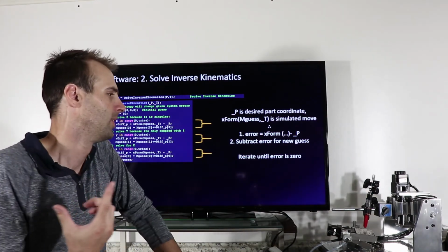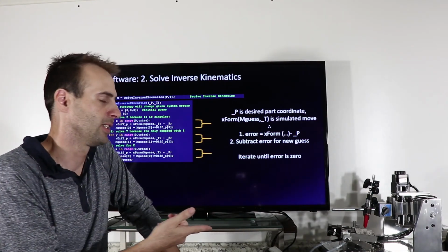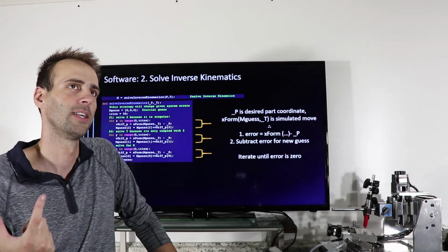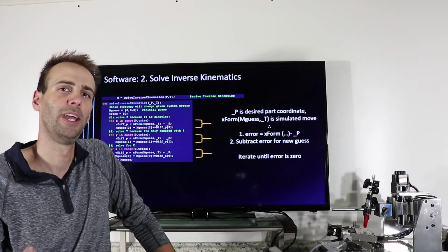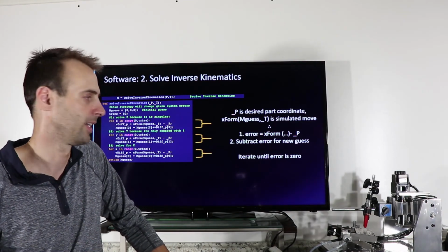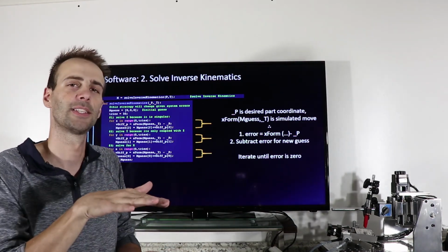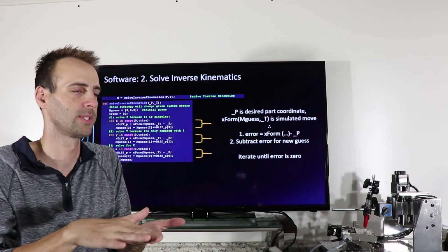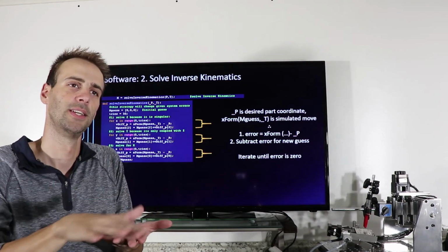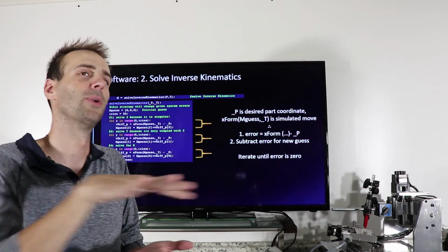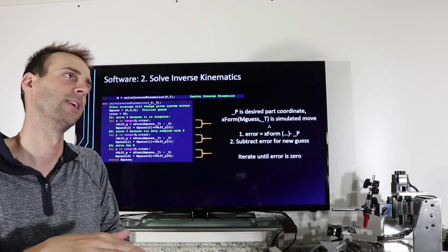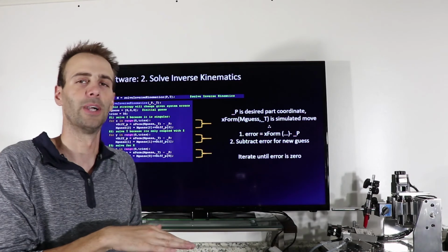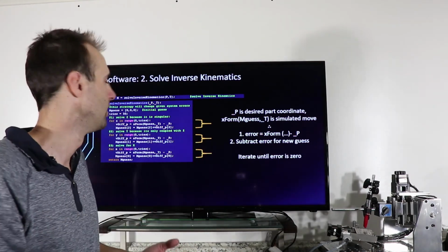And also, the way that this machine is set up, if you think about it really hard, there's certain axes that don't depend on any other axis, right? So, for example, my y-axis is bolted to my x, so of course that matters. My y coordinate is going to matter on my x because there's an error in x, right? So I first have to solve for x and then solve for y.